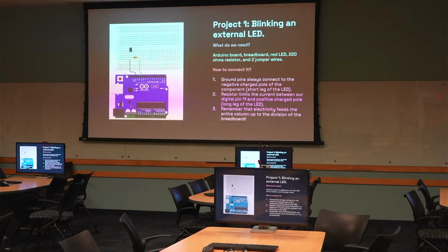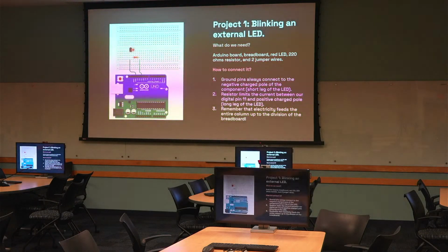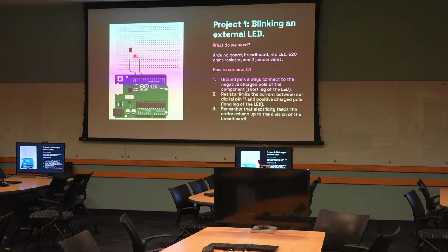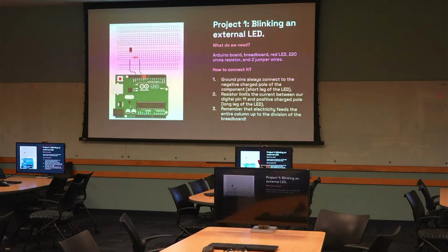Make sure, so this LED, for those that don't know, this is the LED or little light here. We have a longer leg and a shorter leg. Make sure you connect the longer leg to the digital pin, which in this case we're going to be using pin 11, right?